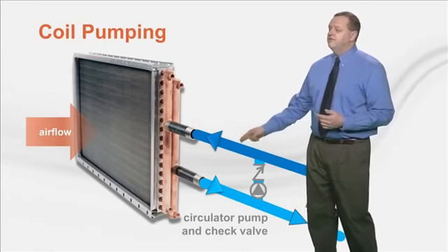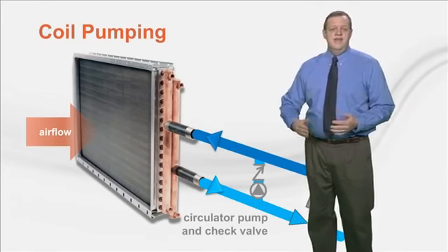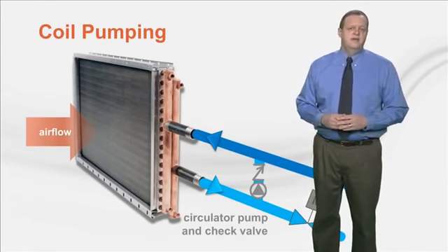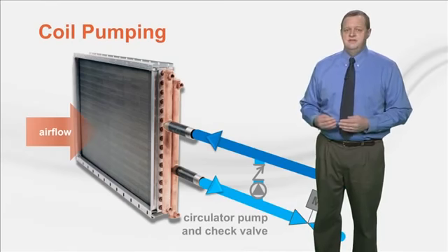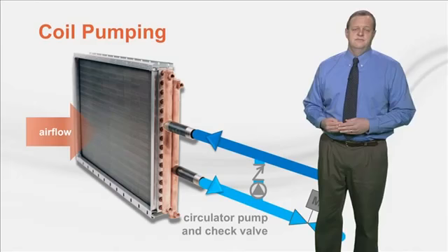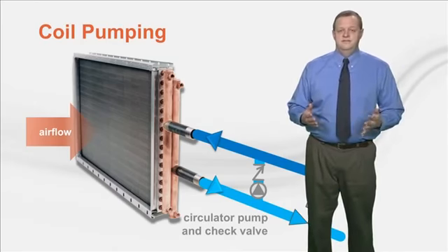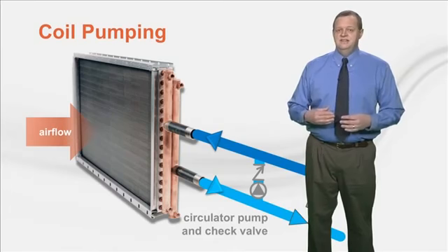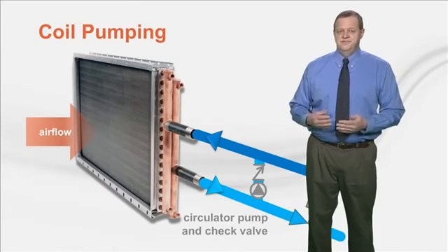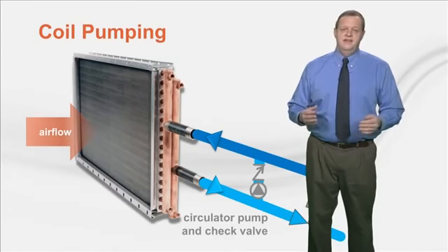This increases the water flow rate through the coil, which can delay but not prevent the process of water freezing. In some applications, in some climates, this may be sufficient. But be careful not to trust the old adage that moving water doesn't freeze. I live in Wisconsin next to the mighty Mississippi River. It freezes over every winter, and I guarantee you that it didn't stop moving.